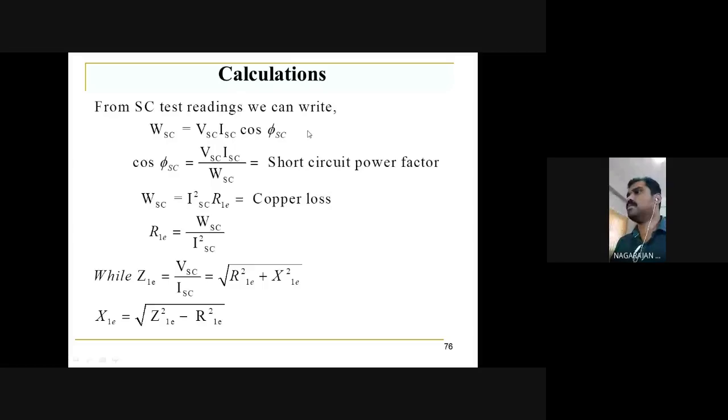Similar to the open circuit test, the power measured here is given as WSC equal to VSC ISC cos phi SC. Look at this notation. The notation has changed.